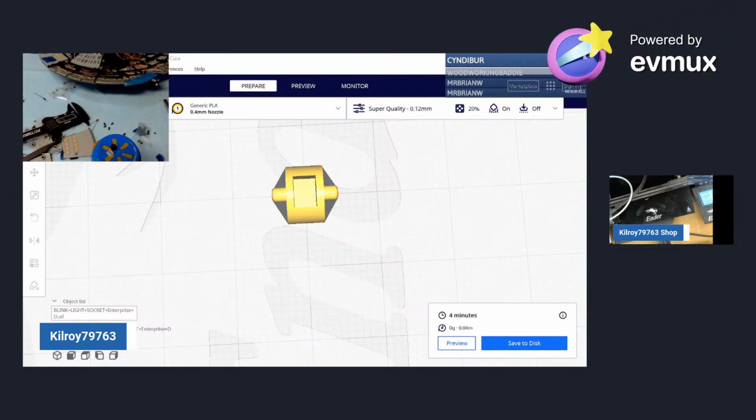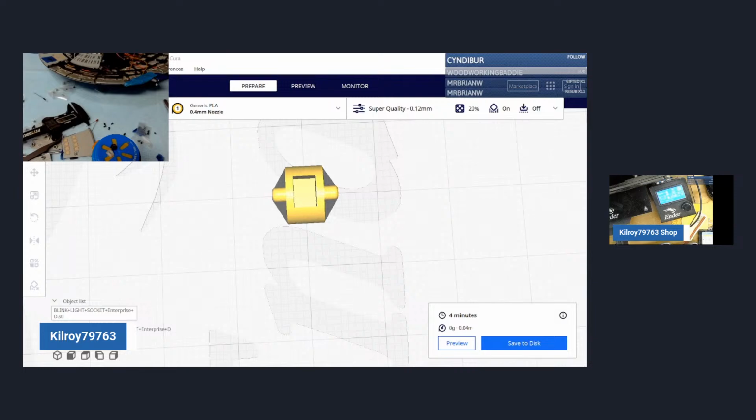The bed is heating, so I don't know if the bed heats and there's no extruder temperature on it right there. Because 50 is, and I know you can't see it, it's tiny on the side, but the bed's heating up. The extruder's right here. It's at 0. I don't know. I think I'm going to have to mark this SD card with a little X. Maybe just stop using it.